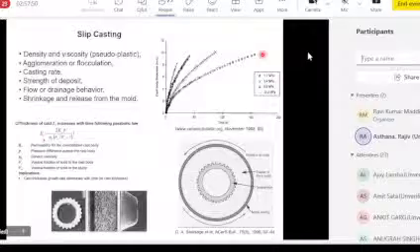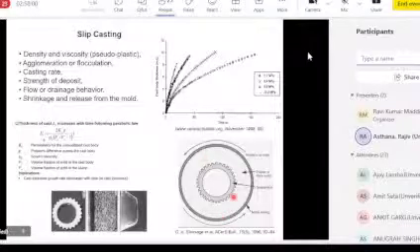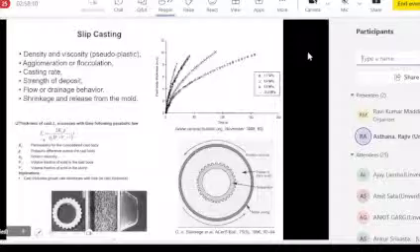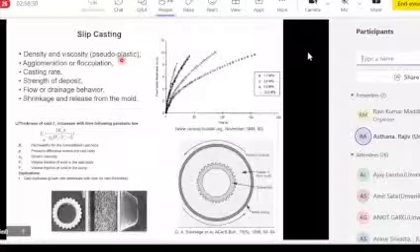So the process slows down with time. But when you apply pressure, higher pressure, then the drainage rate can be increased. Or you can mount the plaster mold on a rotating platform, allow the centrifugal force to drain out the liquid faster. So people try different things to speed up the process. And as we can see, slip casting slurries are pseudoplastic, which means the viscosity depends on the shear rate. Just because you have high volume fraction of the solid particles, the viscosity depends on the shear rate at which the slurry is deformed.